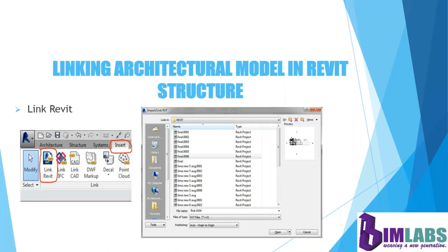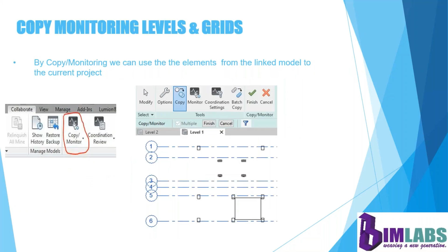So how you can link is in this way. You can just go to the Insert tab and link Revit files. Already in your architectural model, if you create an architectural model in Revit, it will be a 3D model and some columns might already be available, and slabs or floors will also be available.